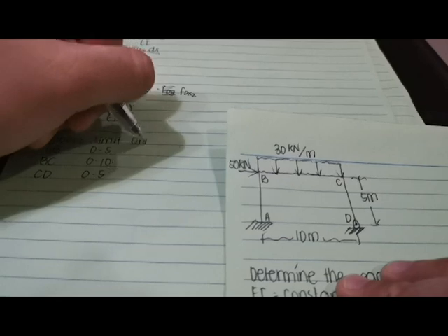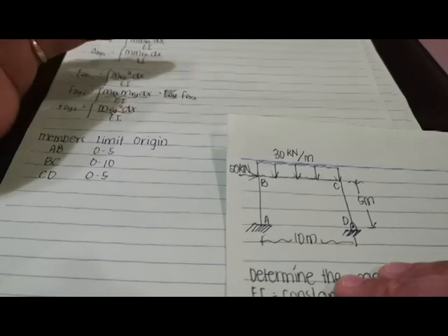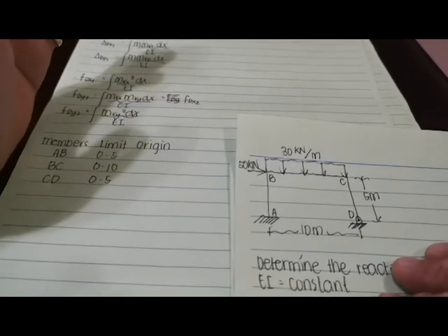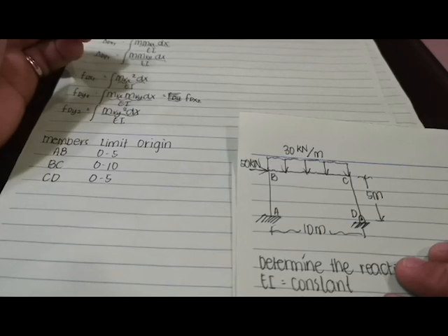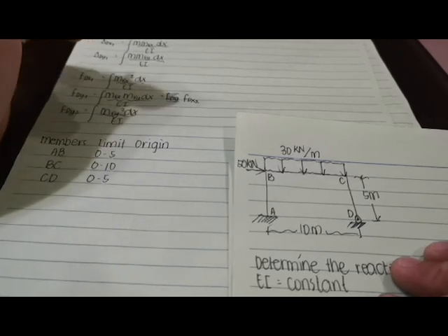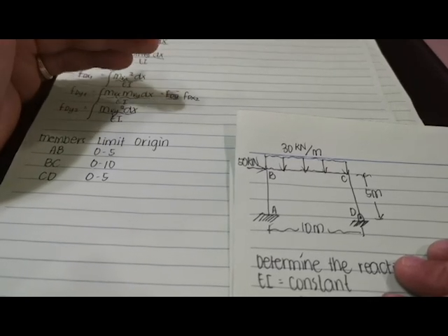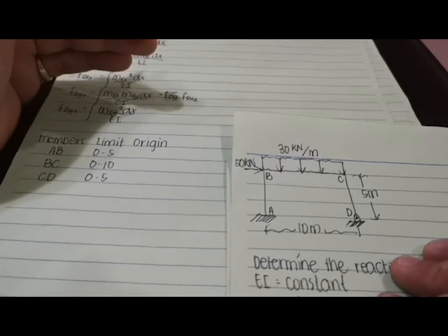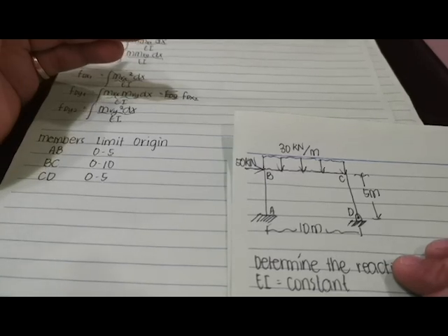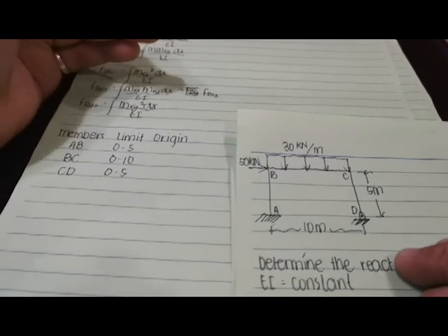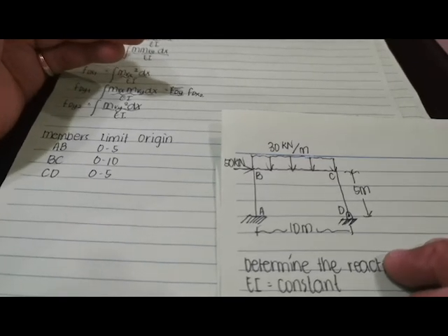For your origin, of course, we need to determine the point where we start measuring the moment. In choosing the origin, you need to choose the point wherein the moment should be at the minimum. Meaning, your moment should be as much as possible 0.